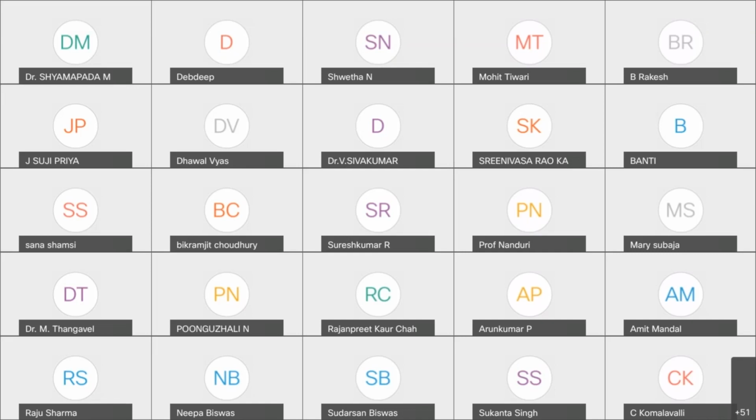The arbiter PUF is based upon a cascade of crossbar switches, which ends with a D flip flop. This is one of the most primitive structures of a PUF, or a delay based PUF, to be more specific.